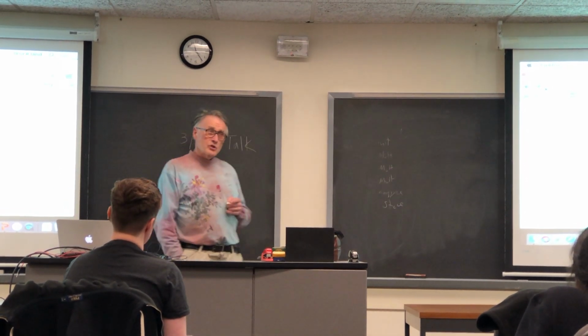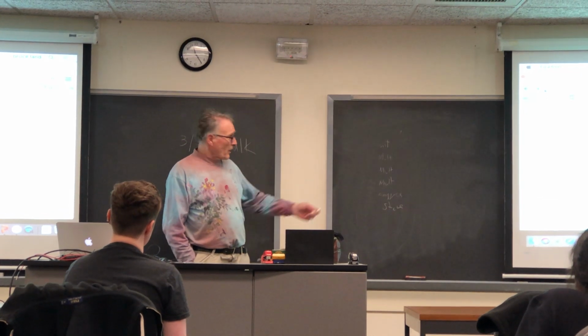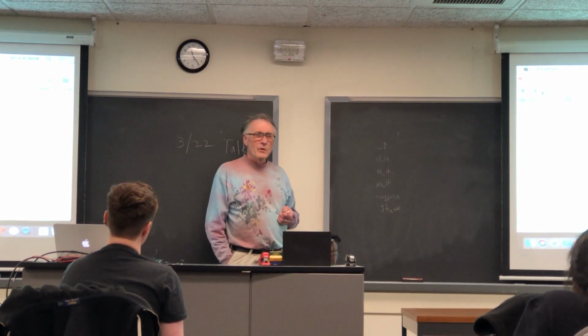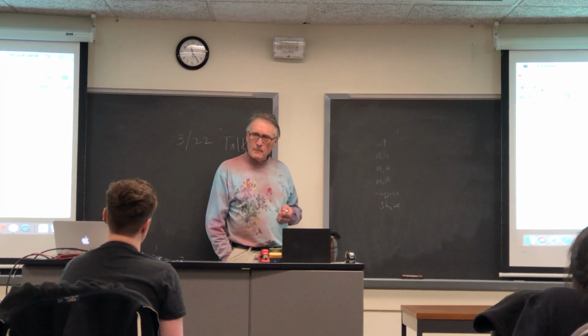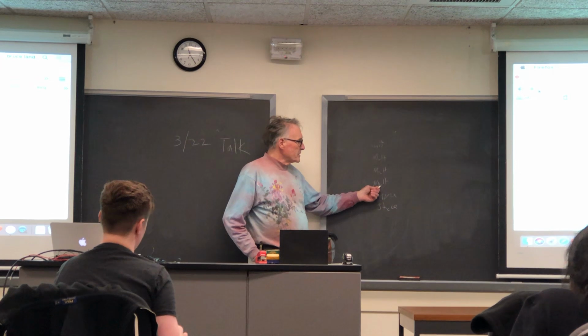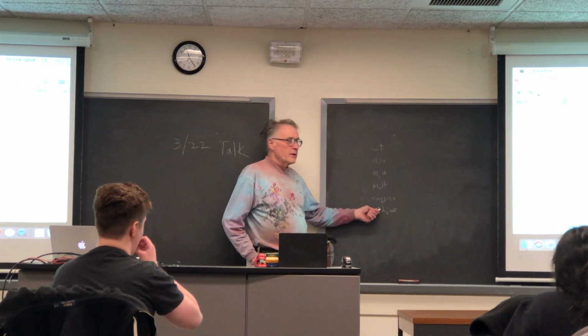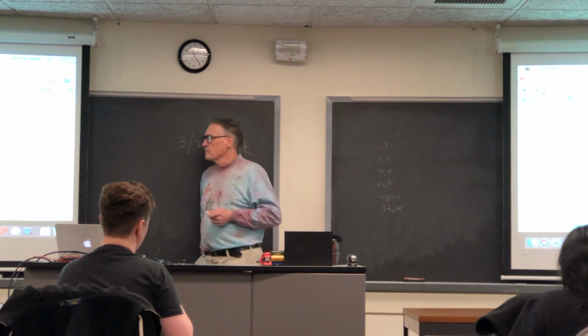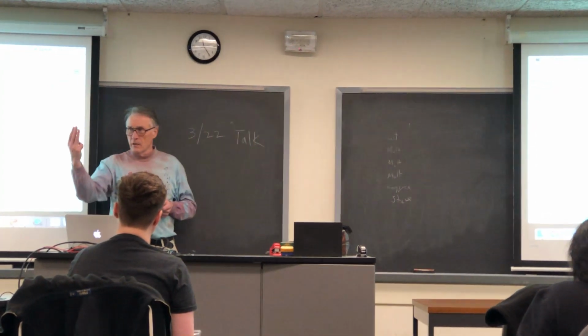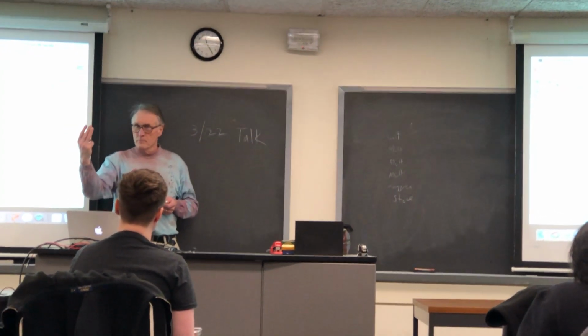Then you say, all right, should you have 3 multipliers per pipe? What if I just used 1 multiplier per pipe and made a sequential pipeline? So you're going to do a mult, then reuse the mult, then reuse it again, then do a compare. Now you can do a sequential pipeline. You can do 3 times as many solvers.